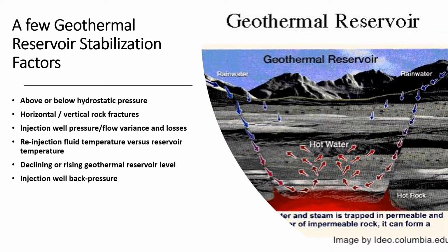Now, as another question, if reinjection fluid temperature injected into a liquid-filled reservoir is the same as reservoir temperature, and permeability between the injection bank and reservoir doesn't vary, pressures tend not to be impacted.